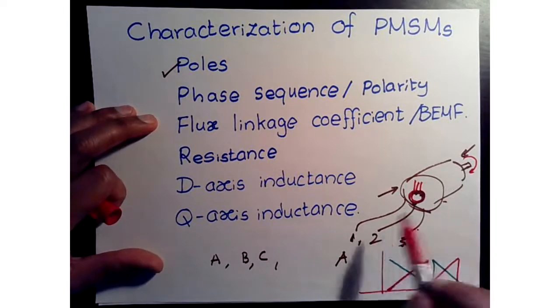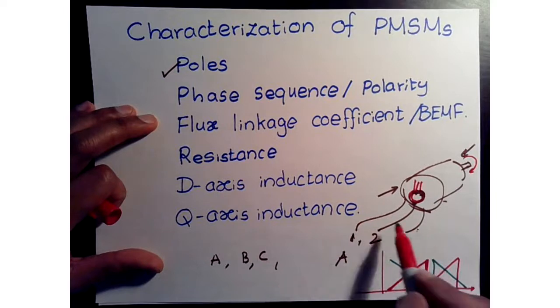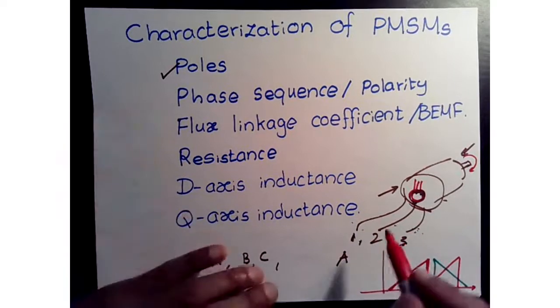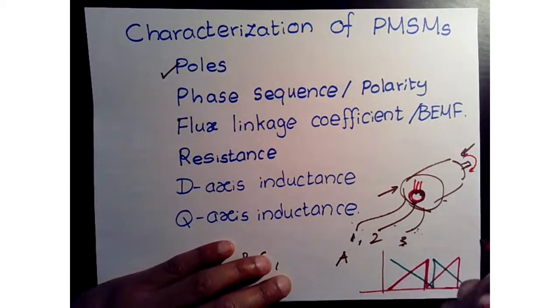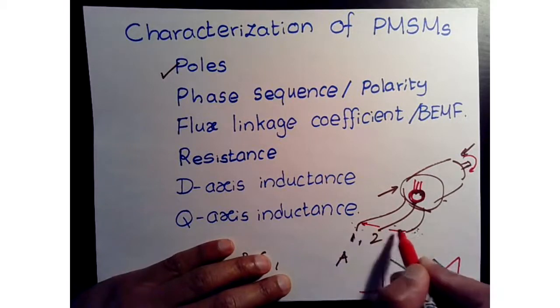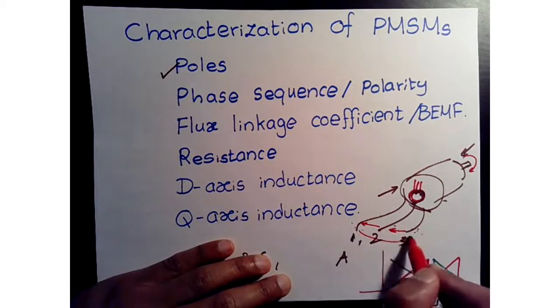And then you can look at how to measure the voltages coming out from these three phases. You'll probably need isolated probes so that you can measure the line-to-line voltages, here to here, and here to here.